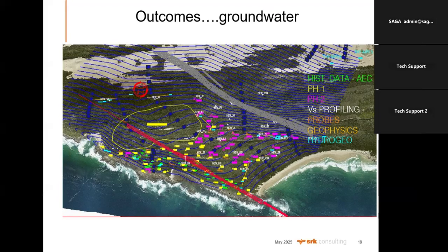than everywhere else. But the nuclear power station will need to be founded on rock from a seismic risk mitigation perspective, which means we have to get through a lot of overburden. We have to dewater that portion, but there's a massive cobble bed lying down there. So how are you going to put in some sort of cut-off system, et cetera? It's an extremely complicated geotechnical challenge.